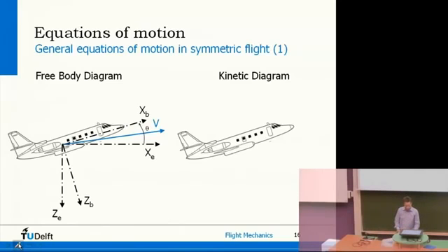and that tells you how much lift and drag the aircraft will generate. So, based on this, you can describe several forces. Lift being perpendicular to the airspeed by definition. Aerodynamic drag, which is parallel to the airspeed vector, but in the opposite direction, of course. Aircraft weight, and finally there's a thrust vector, and the thrust vector will be fixed to the plane depending on how you position the engines. So the thrust vector will also have some kind of an angle of attack.